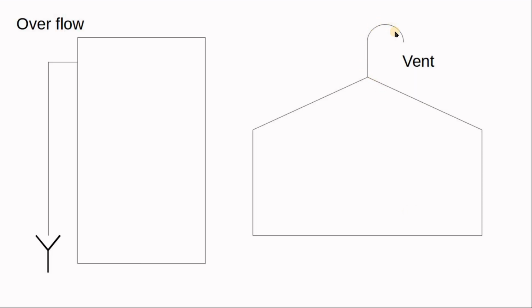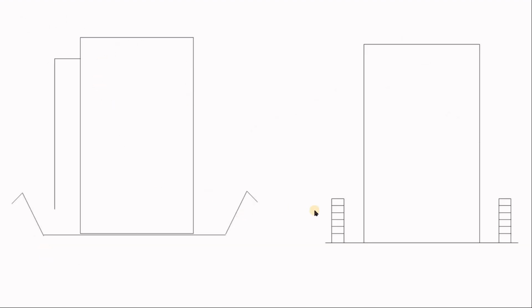In our tank, we may show a vent. We call this a gooseneck vent. This means that your tank is an atmospheric tank. Here we have a vent. We show here an overflow to a ditch or a drain. In this tank, we show something around the tank to protect the surroundings from the corrosive material inside the tank. We build a wall around the tank.